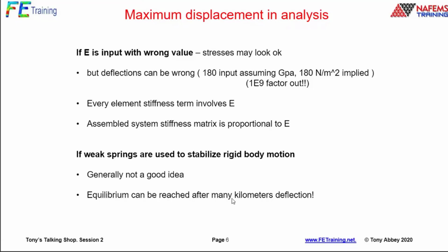And I have literally seen about 30 to 40 kilometers of deflection, because the stresses again could look okay, but the thing is in balance. Imagine a weak spring. The whole thing is in balance because, with such a small spring stiffness, we achieve balance under the loading with many kilometers of deflection. And the trouble is, if we just say, let's say 19e3 meters, well, that's actually 19 kilometers, and it doesn't necessarily resonate. We're just looking at numbers. So I've actually seen those come through.